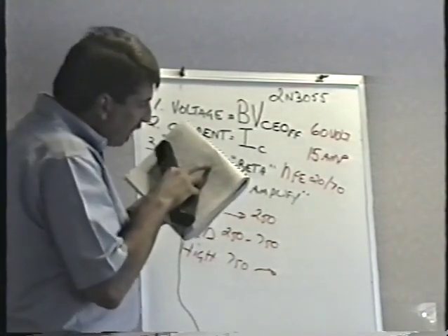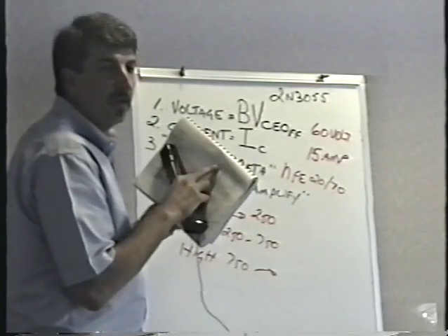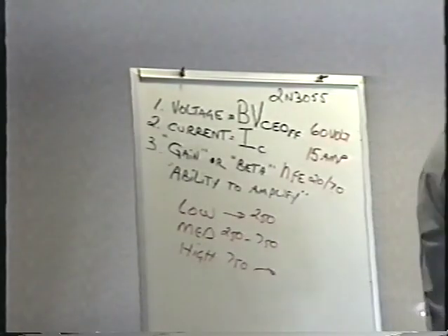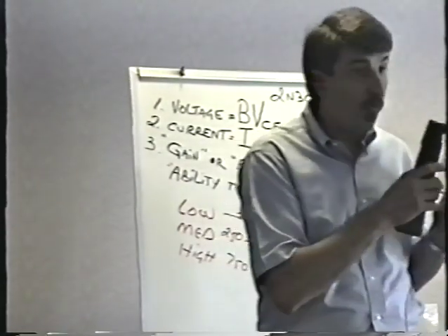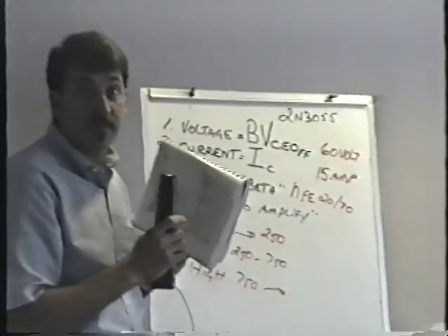How about the one right above it? How about that 2N6576? No. Why not? 2K to 20K. Look at the gain. Sure, the gain says 2K to 20K. That's 2,000 to 20,000. I'd say that is definitely a high gain transistor. There's no question about that.